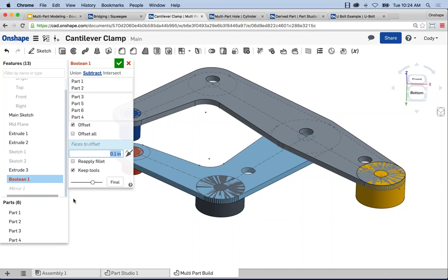But if I want to specify tolerances for the purpose of manufacturing, that's done in the 2D drawing, and you can modify a dimension to do so. So forgive me if I'm not answering that question correctly, but you have the option to offset if you just want to do a simple offset to the geometry, but if you want to specify a tolerance, you'd have to do it in a drawing.